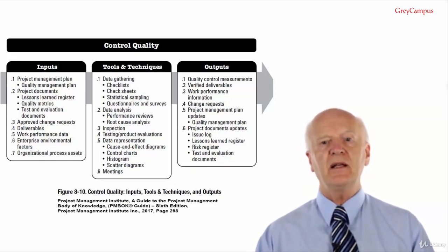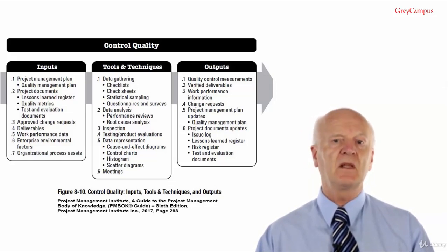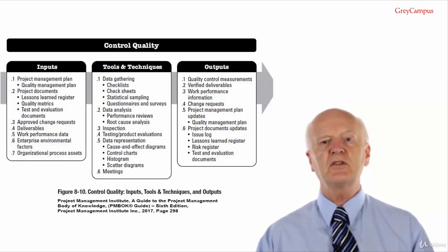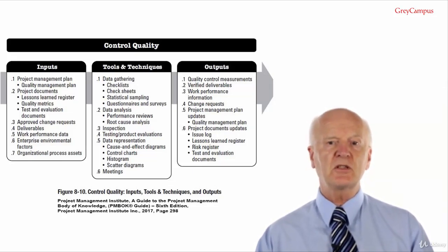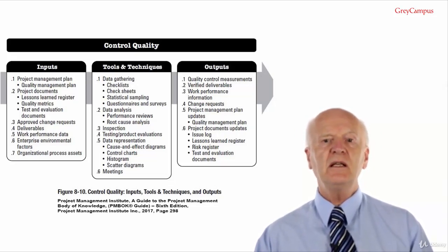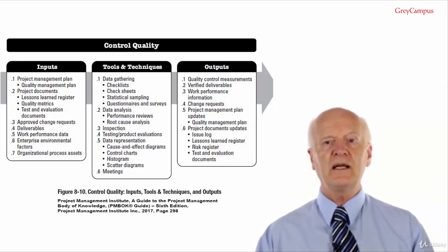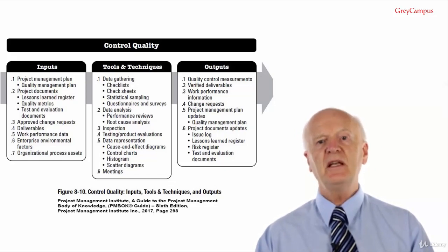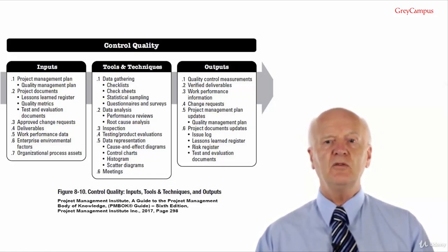Warning: if the engine starts in test 7, stop the engine, abandon all testing and report your findings. 8. Shift the transmission lever to park. It should remain in its position. Report any errors. 9. Rotate the ignition key clockwise 1/4 turn. The engine should start. All lights in the dashboard should extinguish except the park brake light. Report any errors. And so on.